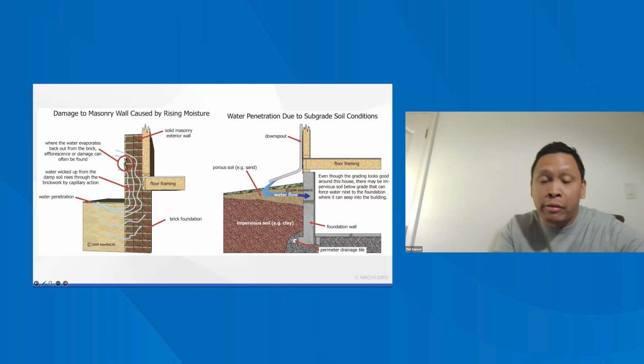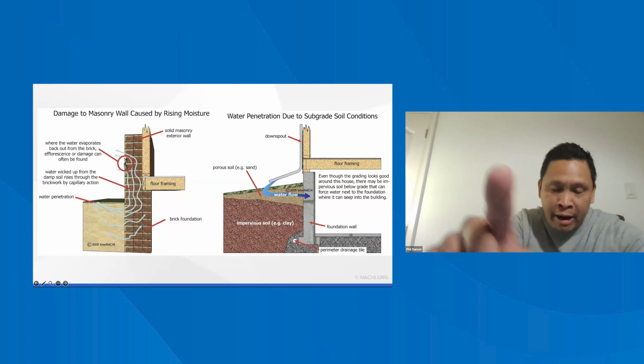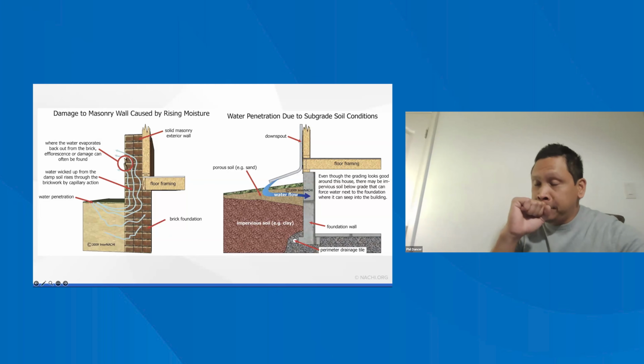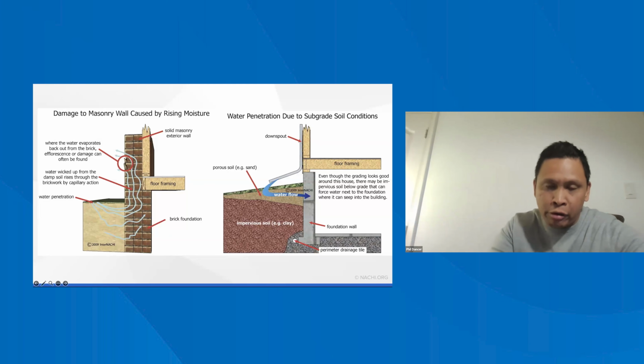And the other thing I've noticed, digressing, since we're talking about capillary action moving upwards: if you're at a resale where you're fortunate enough to see a girder, a big beam made out of wood, resting in a beam pocket, just make sure that there is some type of capillary break between that wood girder beam and the actual concrete beam pocket.